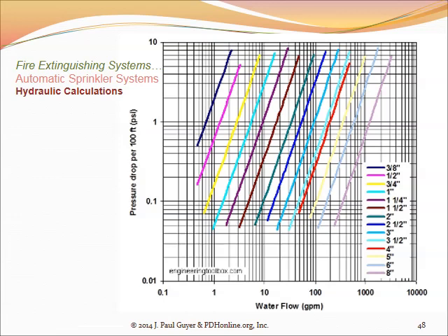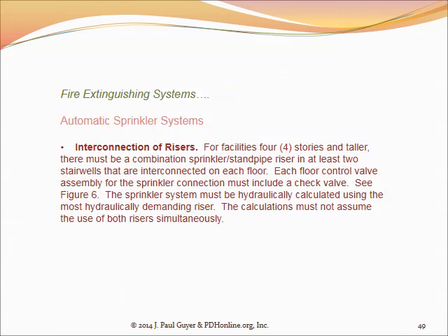So you might increase a 1.5-inch pipe reach to 2 inches, say. So this is how you size the pipes in your distribution system. And I mean, there are different ways, of course, that you could do it, but this is the simple way, and the way you do it all the time, really.